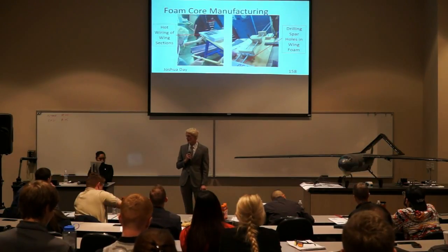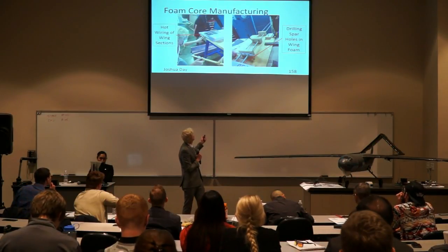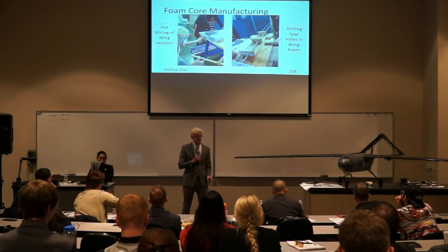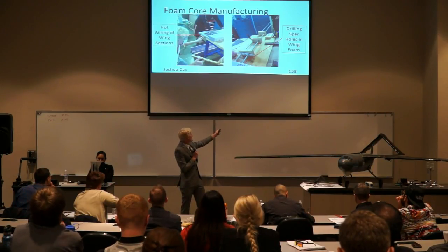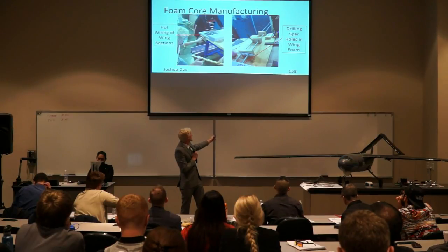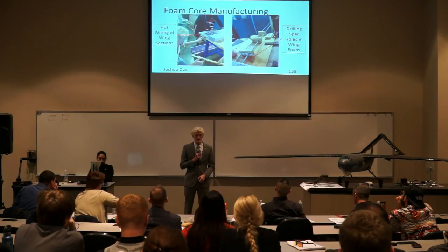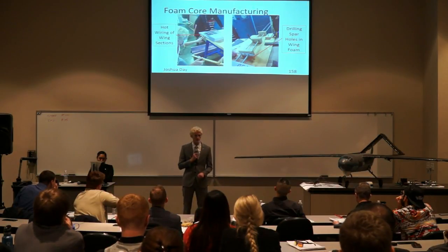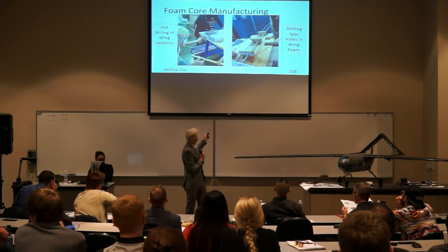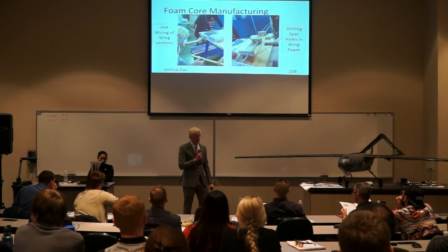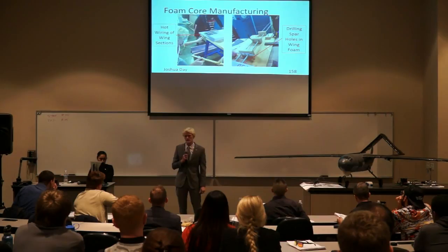The foam core we created by layering 3 layers of the foam on top of each other, and then we attached our aluminum templates and used this cutting jig here in order to drill the spar holes through the foam, and we did that by serrating the edges of the aluminum and then attaching an electric drill and drilling through the foam. We then hot wired those sections using 2 people, and we would cut in small sections and time so that we would get a decent airfoil shape.